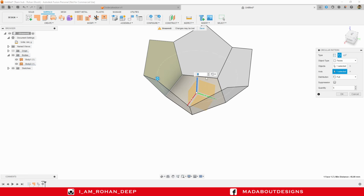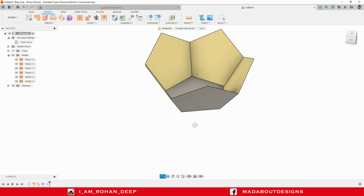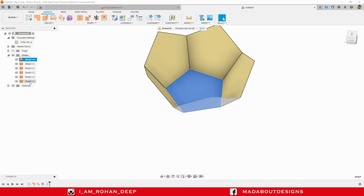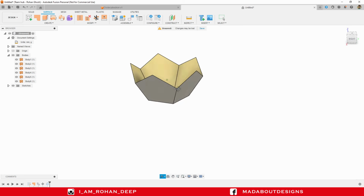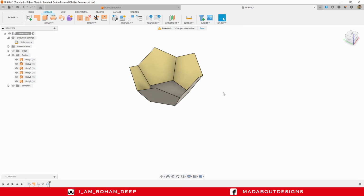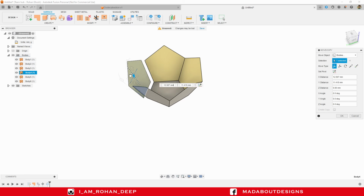Number of items 5. Distribution full, and click OK. Here you can see we have got all our 6 faces, but they are not joined together. As you can see, if I try to move one of the surfaces, I can easily do so.